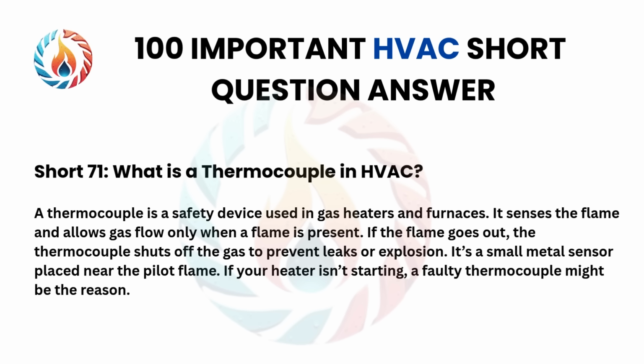Short 71. What is a thermocouple in HVAC? A thermocouple is a safety device used in gas heaters and furnaces. It senses the flame and allows gas flow only when a flame is present. If the flame goes out, the thermocouple shuts off the gas to prevent leaks or explosion. It's a small metal sensor placed near the pilot flame. If your heater isn't starting, a faulty thermocouple might be the reason.